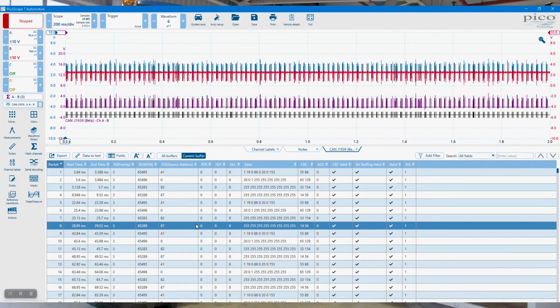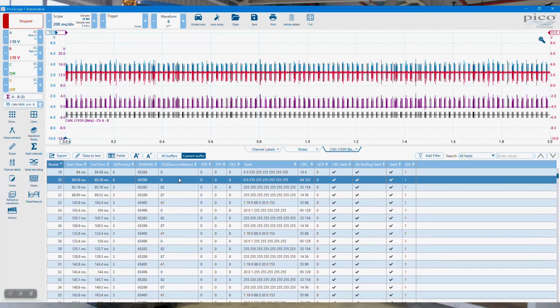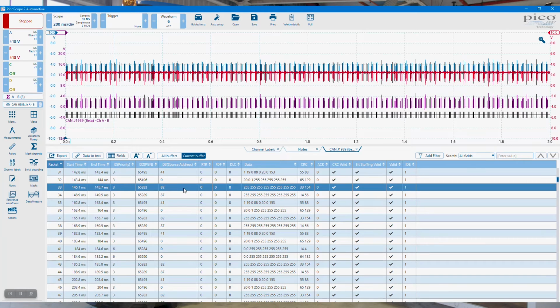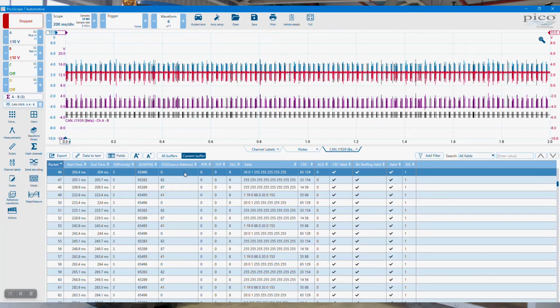Now, that's important when we come to look down the third column, which is our source address. And we can start to see that in this case, again, it's on the after treatment side, so it's a smaller network. There aren't as many ECUs on here. Now, being slightly sad and spending far too long looking at decoding J1939, I can already tell you that the source address 0 is for the engine controller number 1.